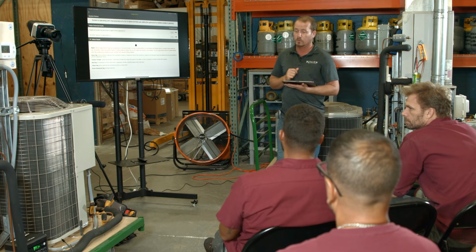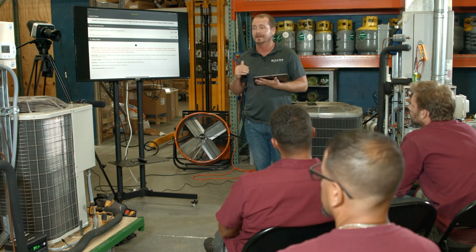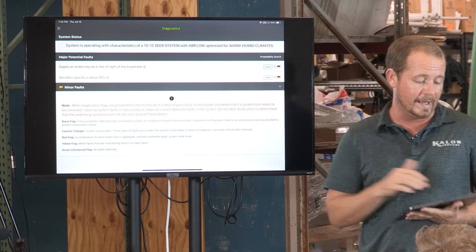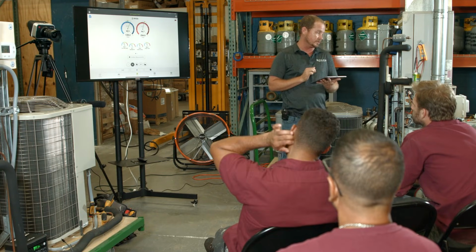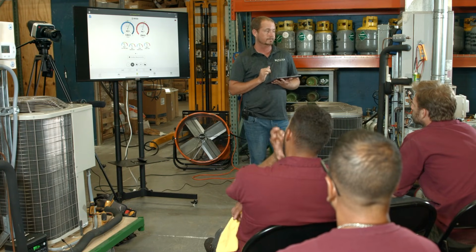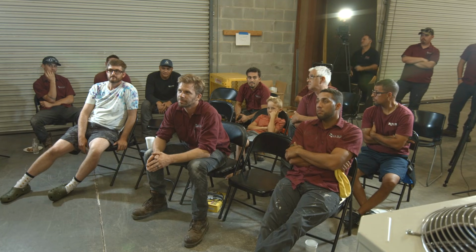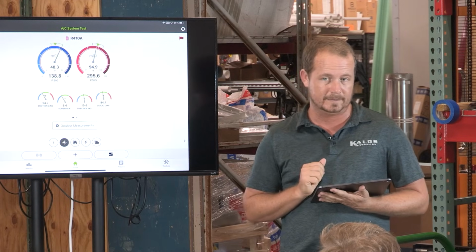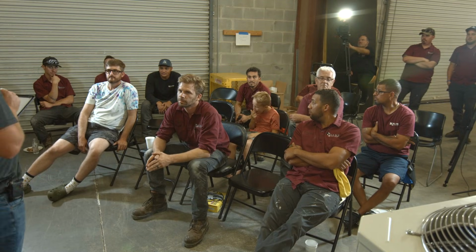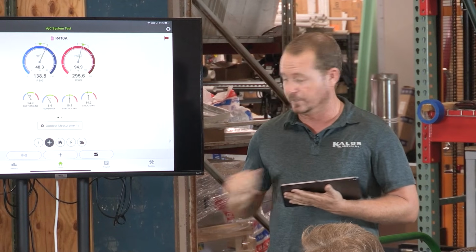Yes. So Corey makes a good point. What would happen if we measured superheat at the evaporator outlet? Would that measurement be higher or lower superheat? On this particular system, probably not much different, because you have almost no line set, but it will be lower. Yeah, it'll be lower.